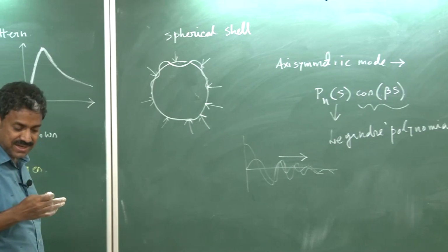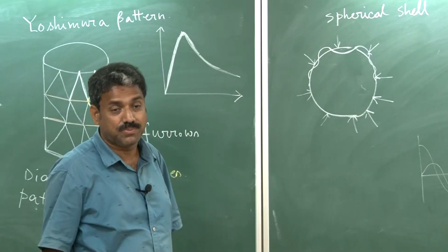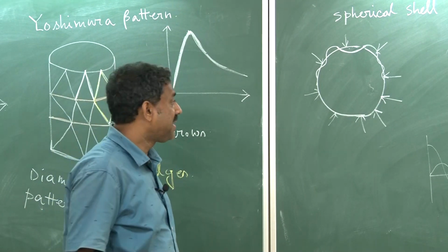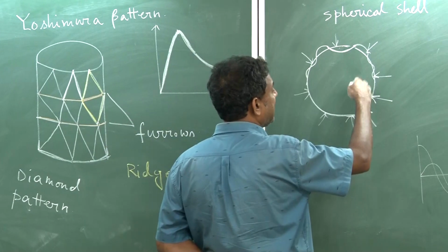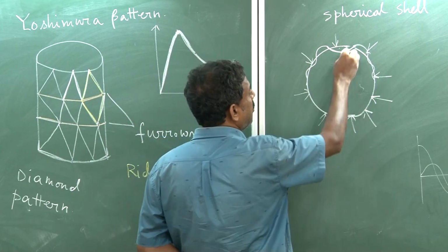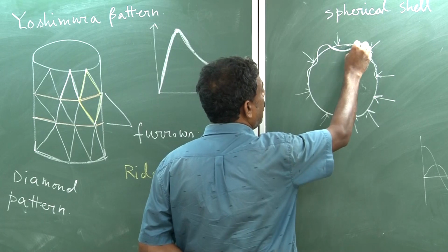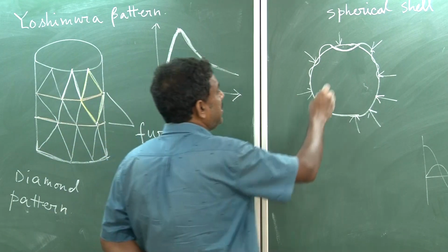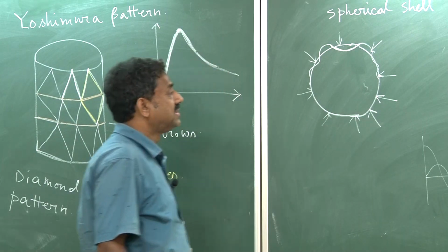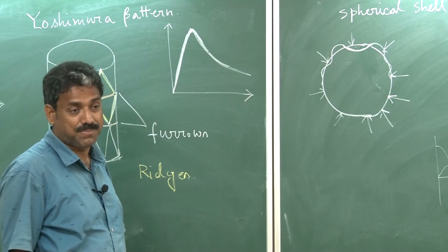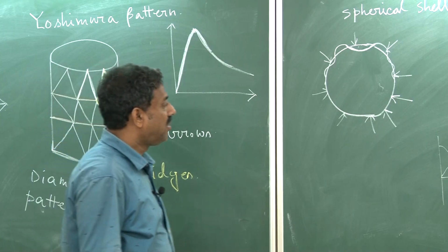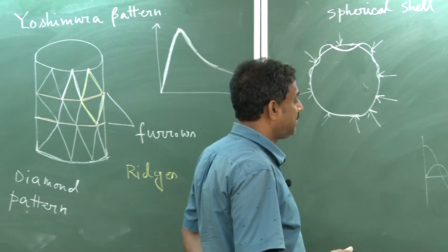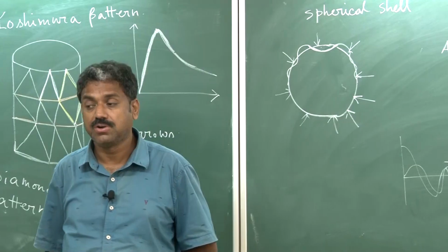So, if you go a little beyond in the post critical regime, what happens? Abrupt. Initially the global buckling mode will localize at the top. So, all displacement can be localized. Essentially, we will see that this kind of elastic localization occurs in the spherical shell, and that is kind of abrupt. So, post critical. This analysis has been presented by various people like Hutchinson and others.